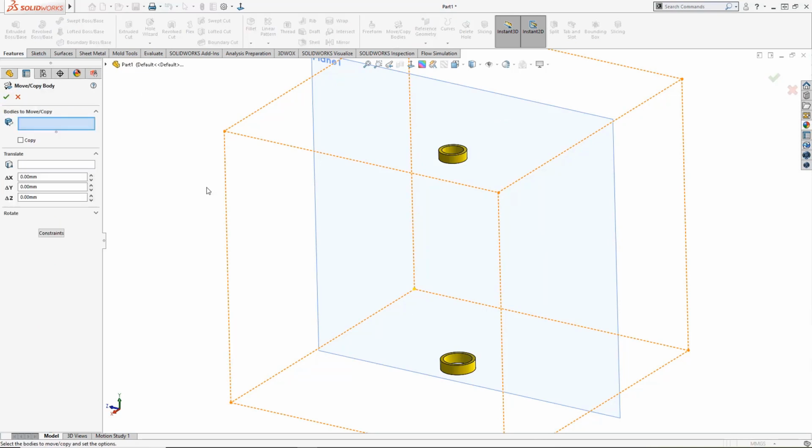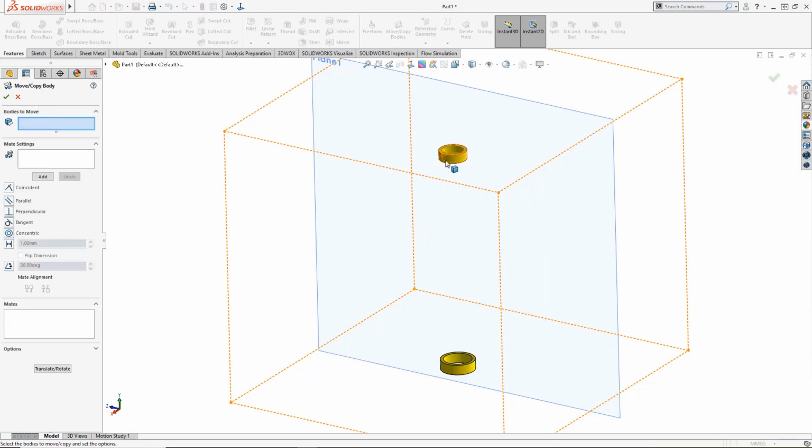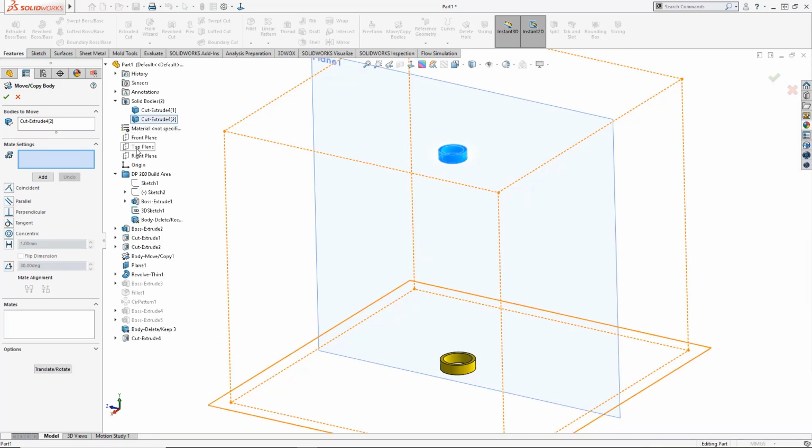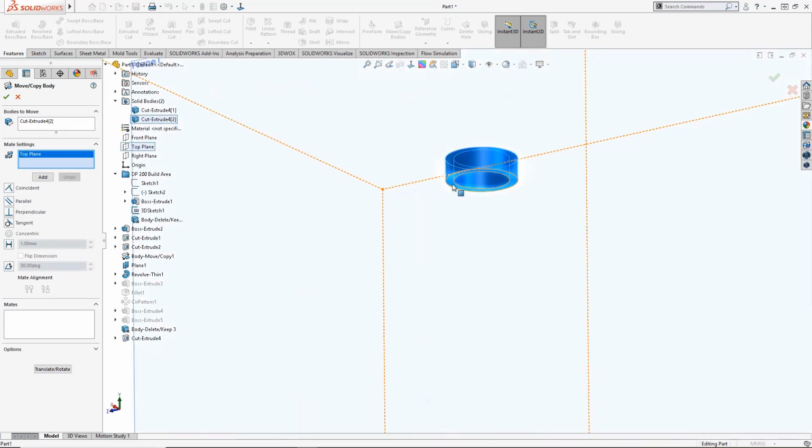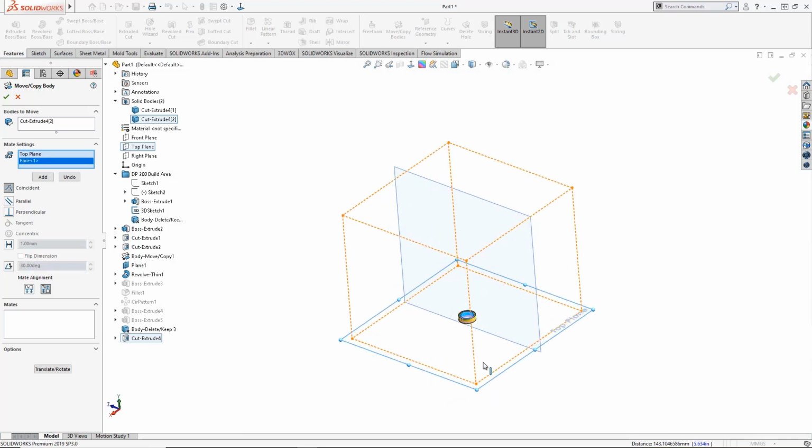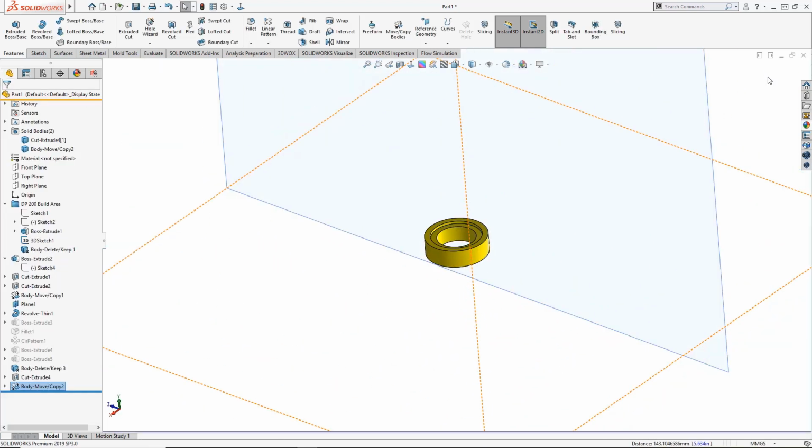And even though the dimension is accurate on screen, because of the way it squeezes plastic out or the way that you might have some overruns here and there, you want to go ahead and make sure that this thing's going to print up properly. And I'm just going to do that by printing a 10-minute print here with a couple of simple rings.